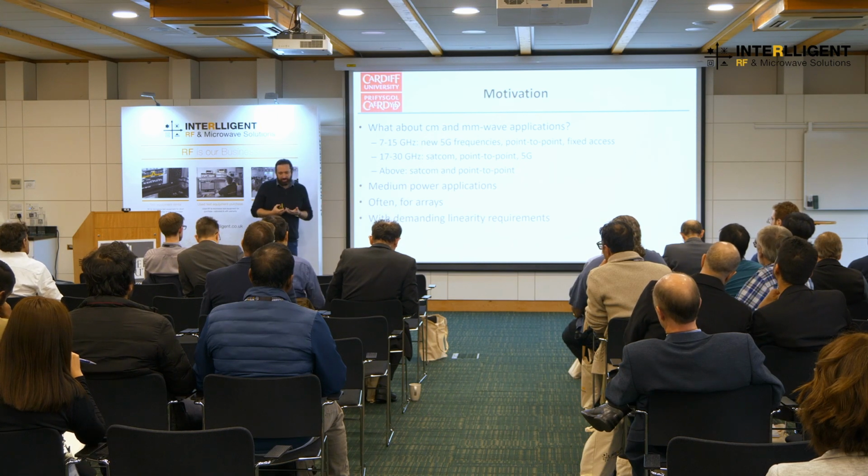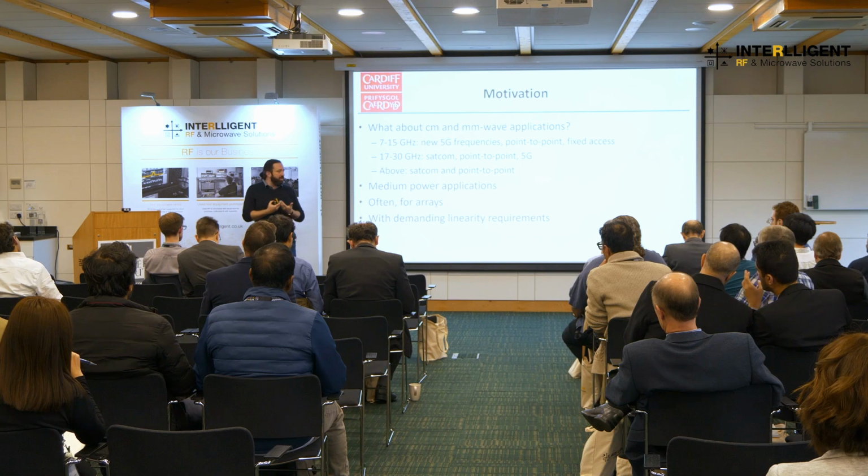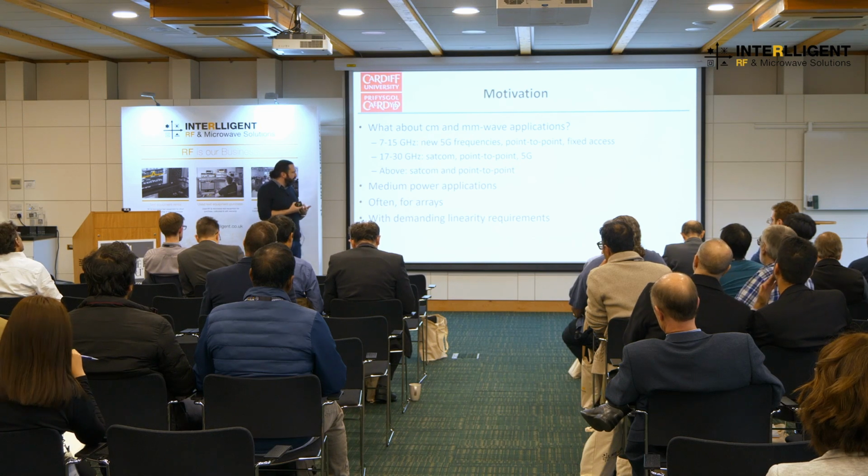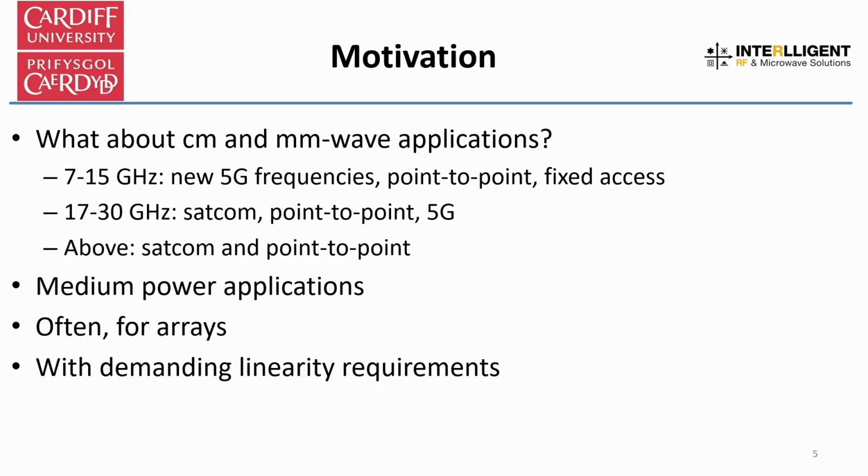Above that, I don't know if Doherty will ever be applicable, maybe, but clearly SATCOM is a big one there, as are point-to-point links, and backhauling in general could be useful for telecom. These are medium to lower power applications, so we're not talking hundreds of watts, we're talking maybe 10 watts peak output power, 20 watts, and very often power amplifiers that will be integrated in arrays, larger or smaller.